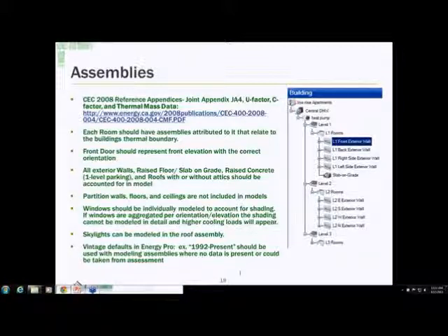But there are errors that will stop you. For example, if you set the occupancy type to multifamily and you're actually doing a high-rise calculation, it will stop you and say, no, I can't do this calculation because you have the occupancy set to multifamily, not high-rise. And you have to go in and change that in order to run the calculations.